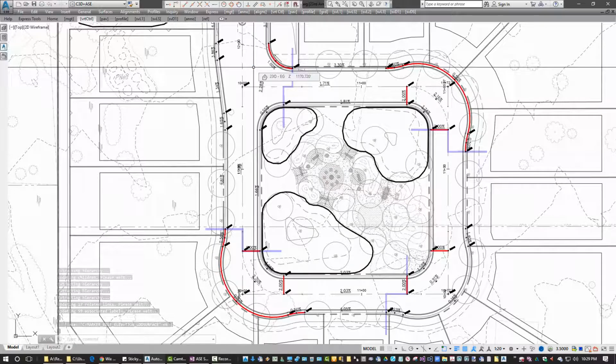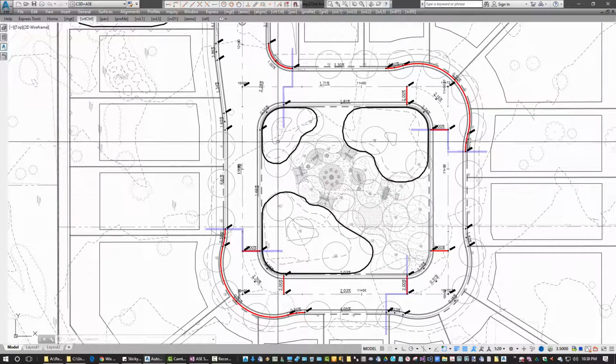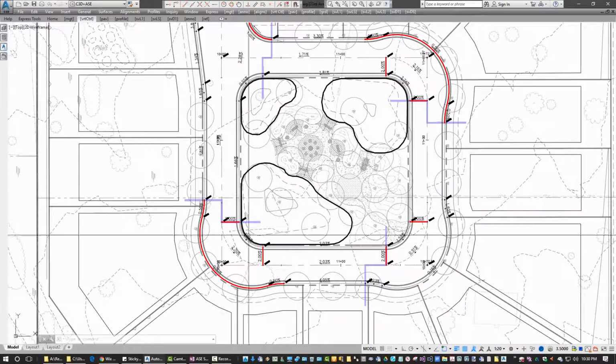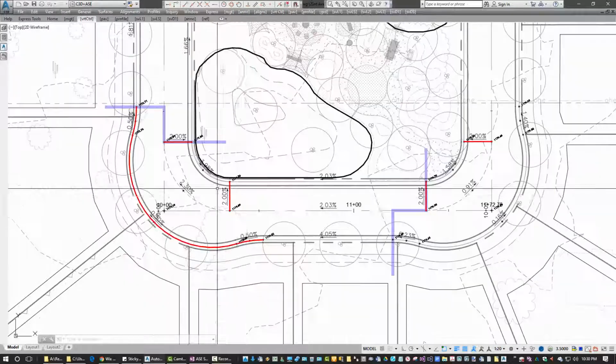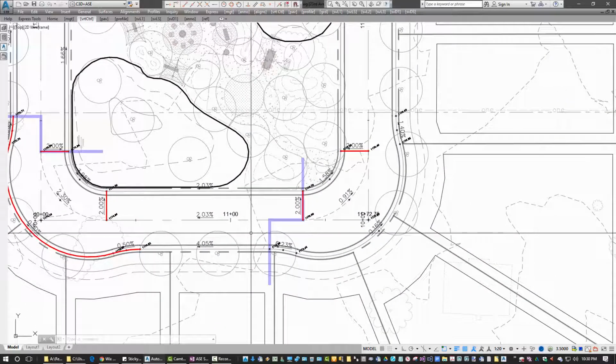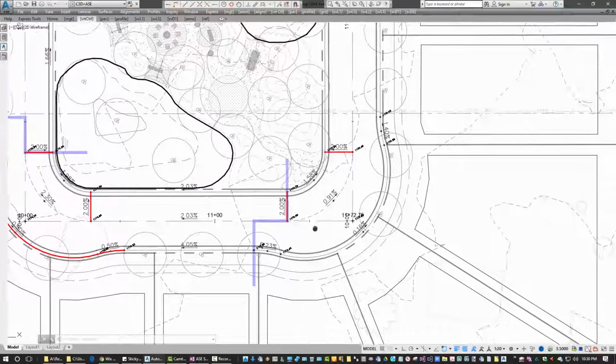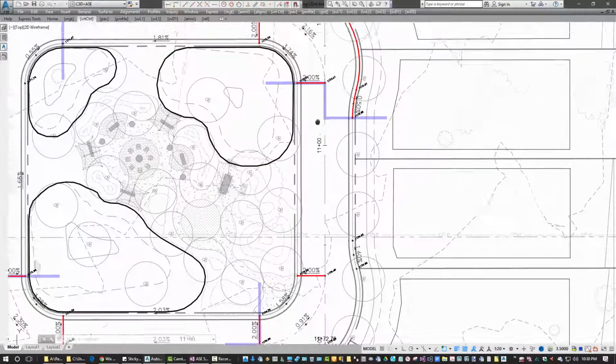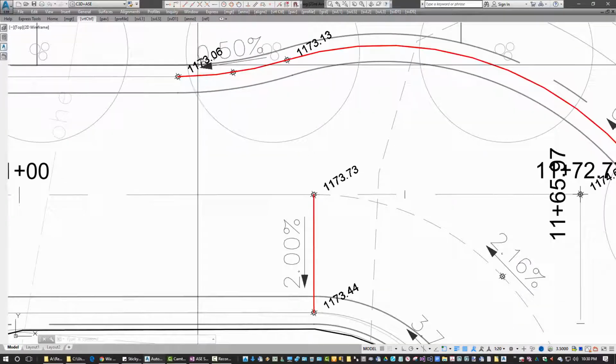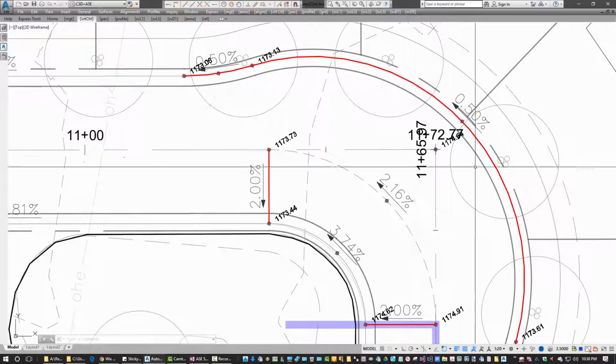The direction of the flow labels right now will indicate where the water is naturally draining. And that would be any flow label that is not constrained. Like these are always going to be 2%. As we talked about before, we've got 1173 here now, but we've still got 0.5% going through this knuckle.